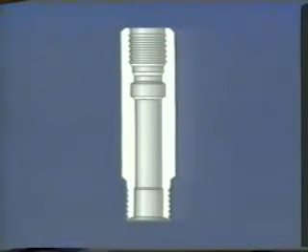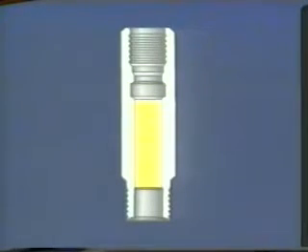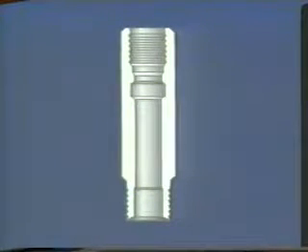The Model F nipple has a simple groove machined internally for the locking profile and a packing bore below the locking profile. The Model R nipple is similar in design to the F nipple, but has a no-go restriction machined into the nipple below the packing bore. The Baker nipple system is a running tool selective system. As many F nipples as necessary of the same size may be run in the tubing string.